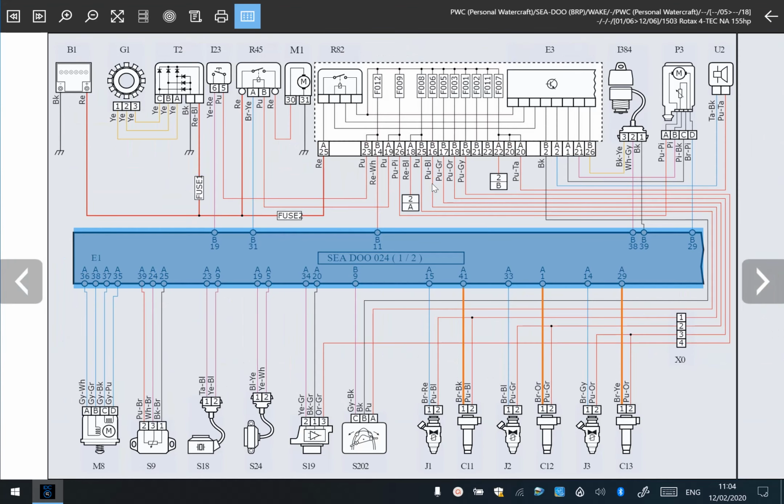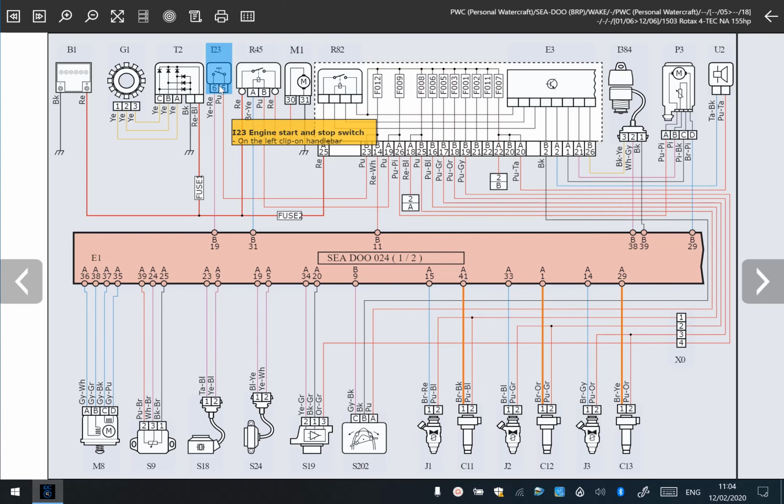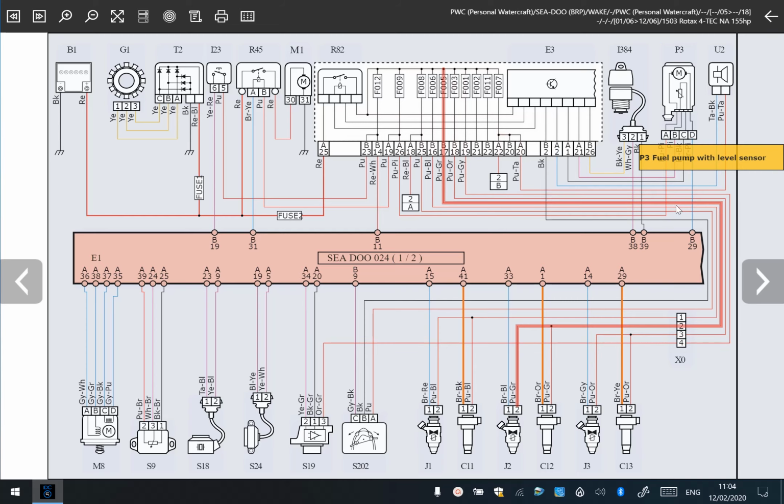These are made in-house by Texa. They're all interactive, as you can see as I'm scrolling along. A description comes up, and on occasion it also tells you where that component is. If you notice, when you're hovering, you can see the communication line, so you can see what's connected, which is going to help your diagnosis.